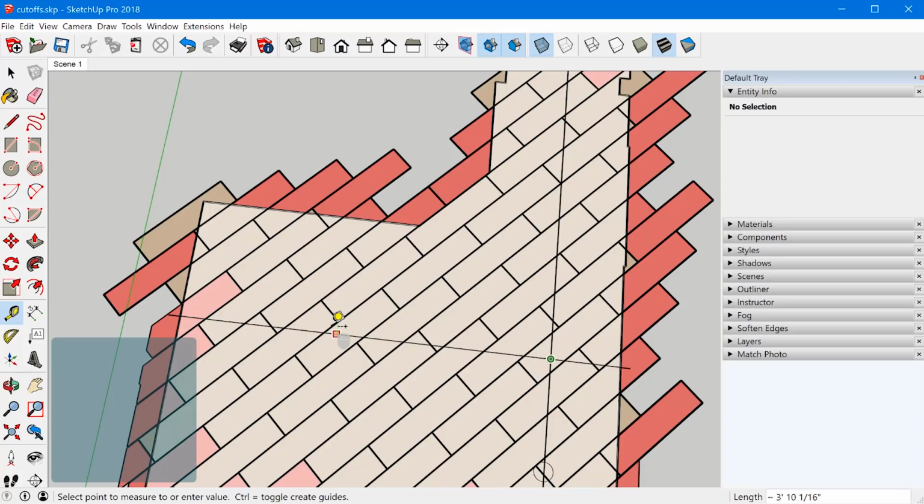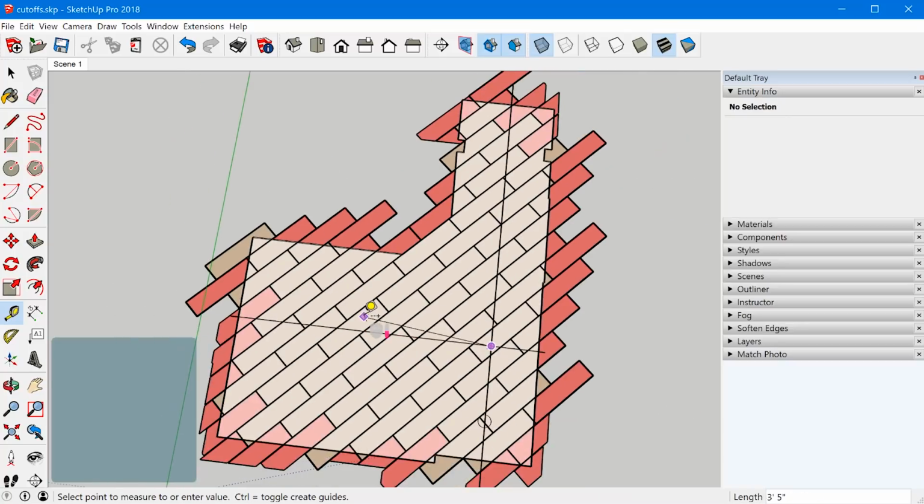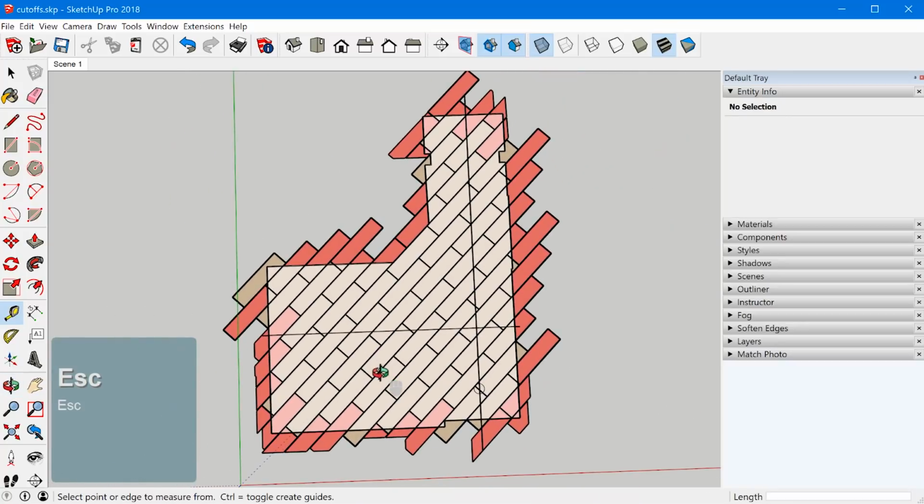So I went into the bathroom and I measured from those chalk lines that were snapped on the floor, 4 feet and 7/8. I did the same thing in this direction. If you remember, I had to rotate it slightly off 45 degrees, so it wasn't exactly square. So I got a slightly different measurement there. And then from there, you can use the 3-4-5 method to establish your diagonal grout line reference lines that you're going to snap on the floor to align your tile to.